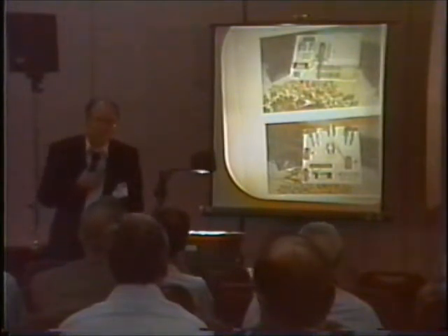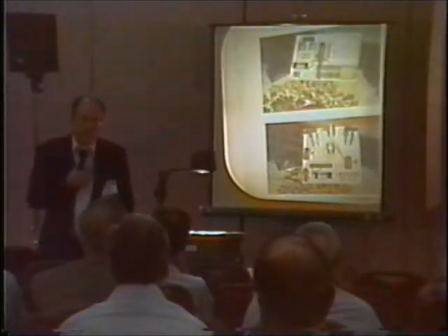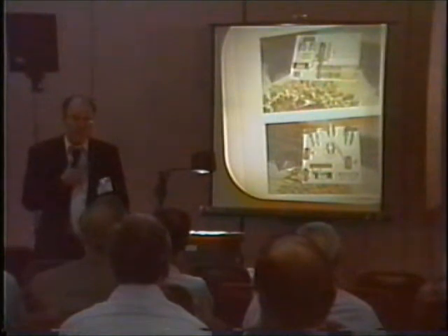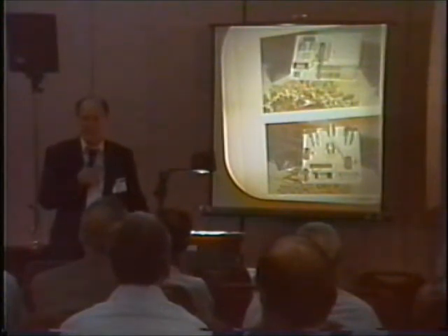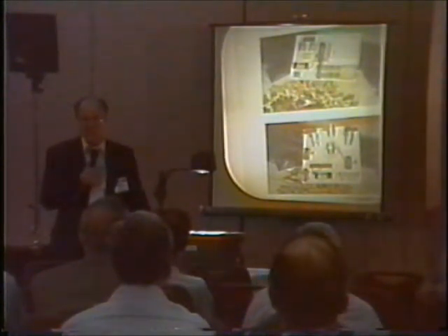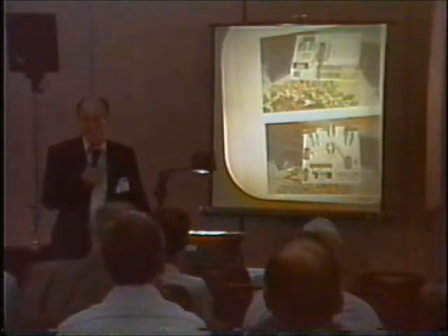A resistor in series with a neon bulb? Can you use 1,000 ohm? You said 47,000? That's what I measured on one of them. They didn't specify on the package. That's pretty well standard for, I think, a 240 volt neon indicator. Anyhow, the bulb lights up very brightly, and you have no trouble at all. It takes 70 watts, I think, to light the thing, something like that.